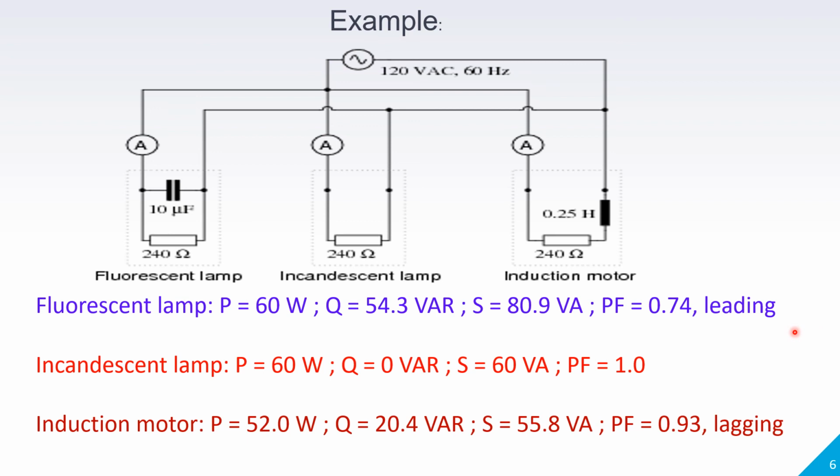So this is how today we have seen all the three types of power, that is active power, reactive power and apparent power. Formulas: for active power VI cos phi, reactive power VI sin phi and apparent power V into I. If the power factor is lagging, then to give the same output, more current will be required and input power has to be increased.